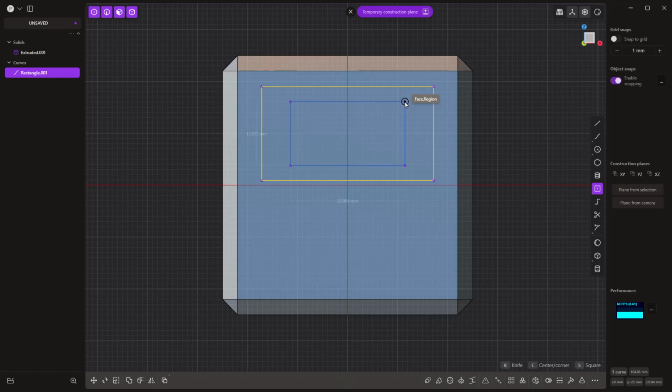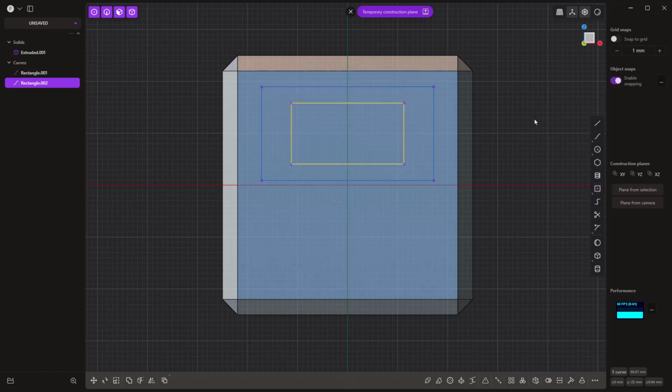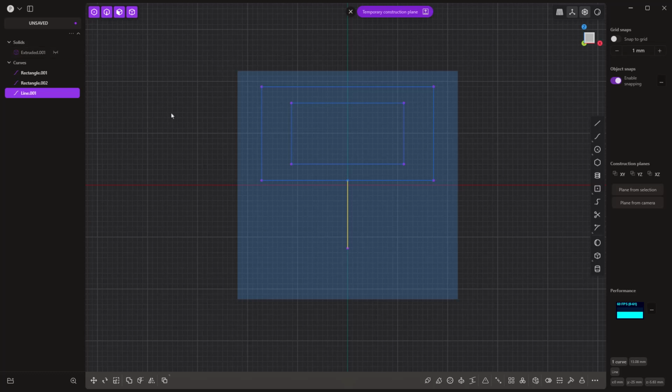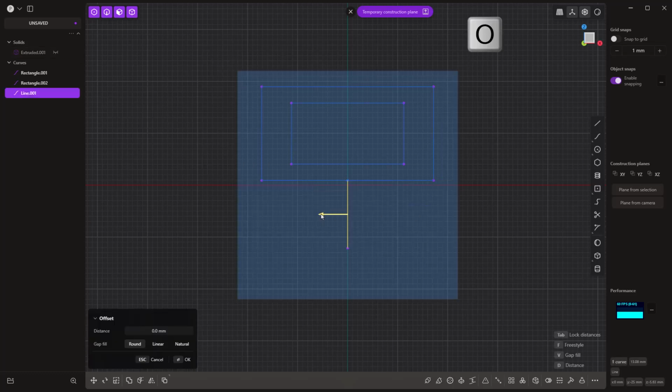And with the question mark block, you typically have a thinner section at the top and thicker on the sides. So just do this visually, not using numbers. Right click to accept. Then we'll use our line tool from the midpoint, bring it down to where you think the question mark should end. Left click to accept. And because this is going to be easier to see, let's go ahead and hide the block. And now we want to take this line, hit O to offset, begin pulling it out and hit Tab. And just kind of make it visually the same as the width of the side.